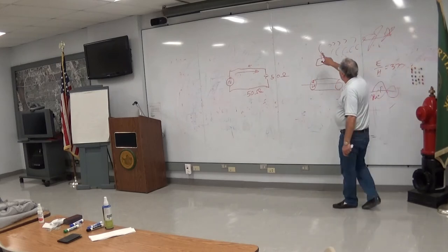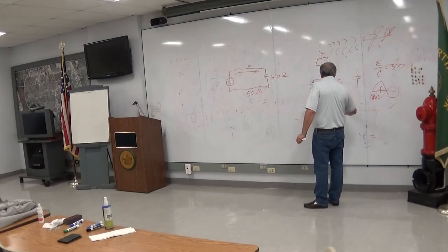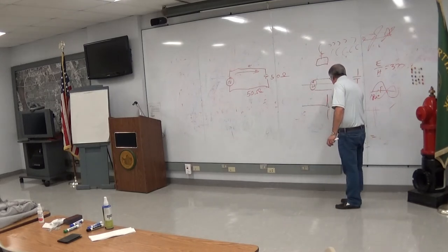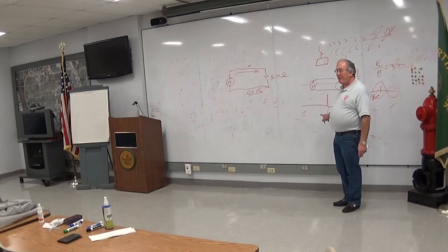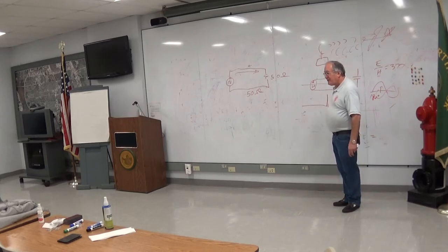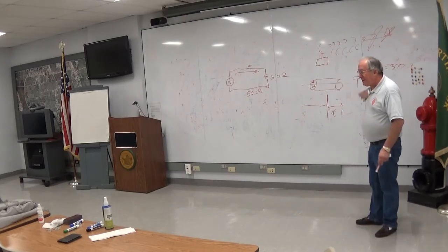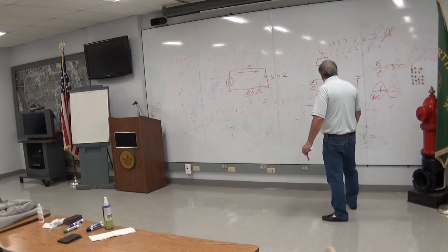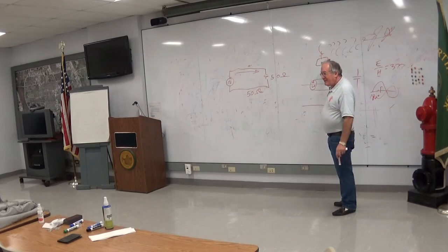And of course, the antenna is ready to receive it because it sends out a pulse and waits for an echo. The timing of that pulse tells it how far it is. You get about 25, for every mile it takes about 25 microseconds for that signal to make the round trip. If you do the math, speed of light, distance, and all that. So how far you are determines the timing of the echo, and of course which direction the antenna is pointed when it sees that airplane tells it the direction.